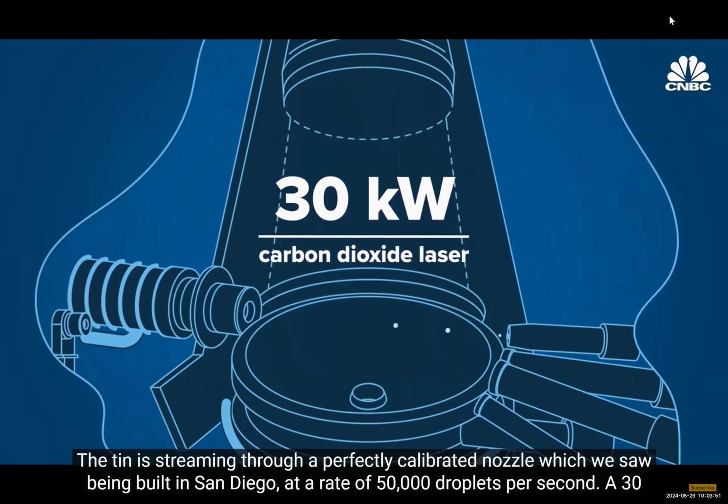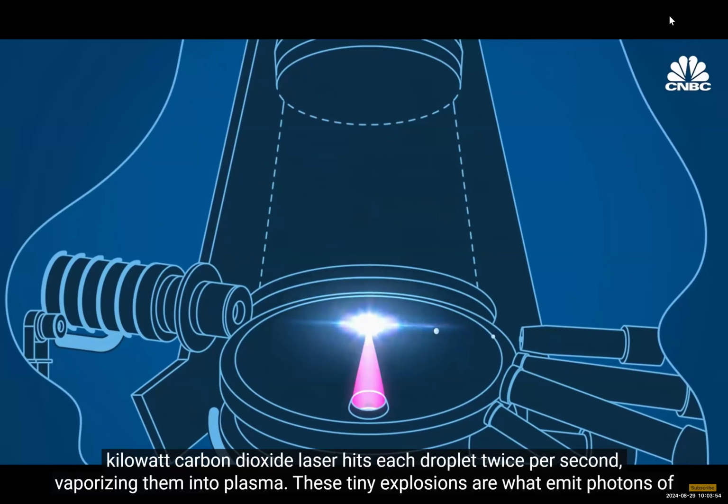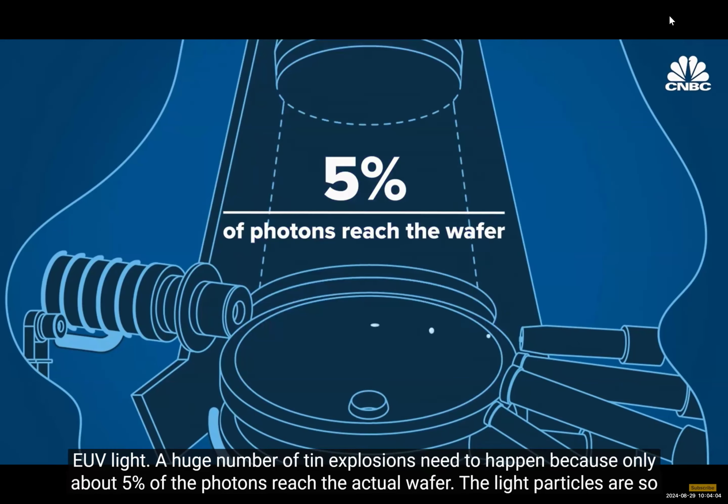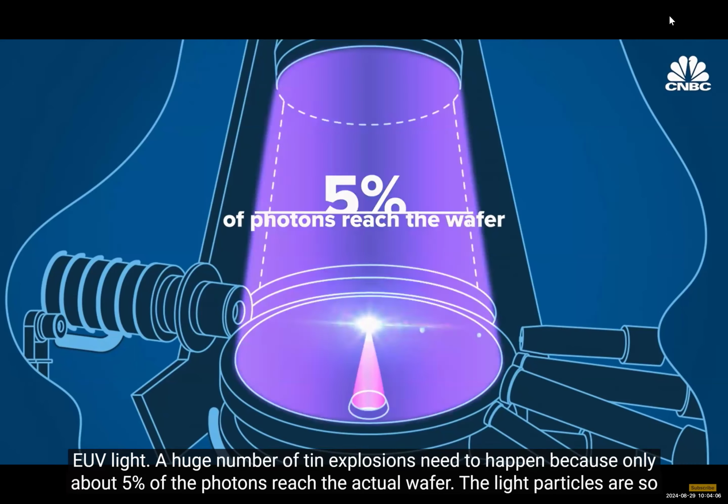A 30 kilowatt carbon dioxide laser hits each droplet twice per second, vaporizing them into plasma. These tiny explosions are what emit photons of EUV light. A huge number of tin explosions need to happen because only about 5% of the photons reach the actual wafer.